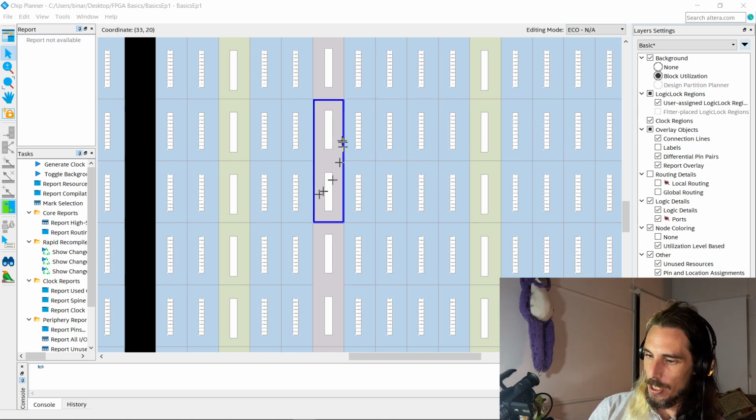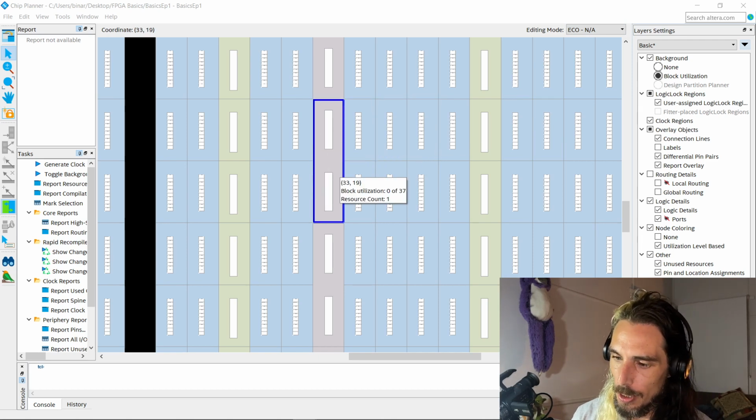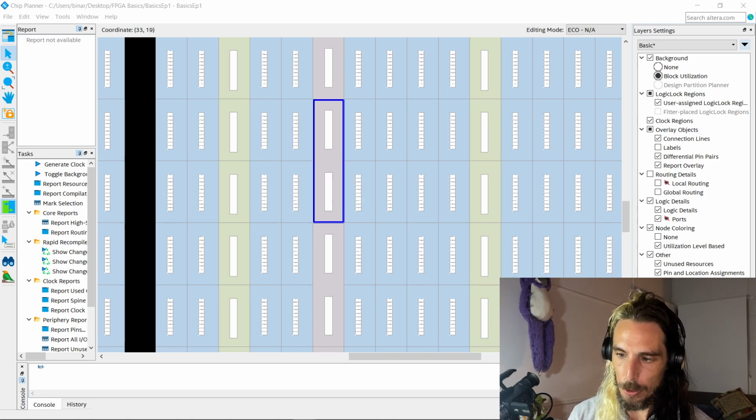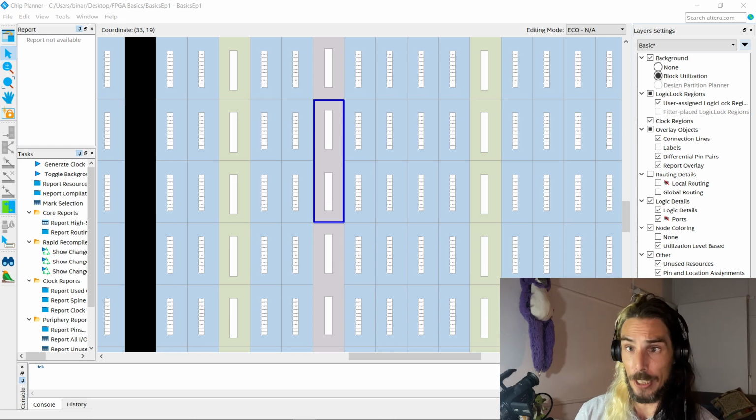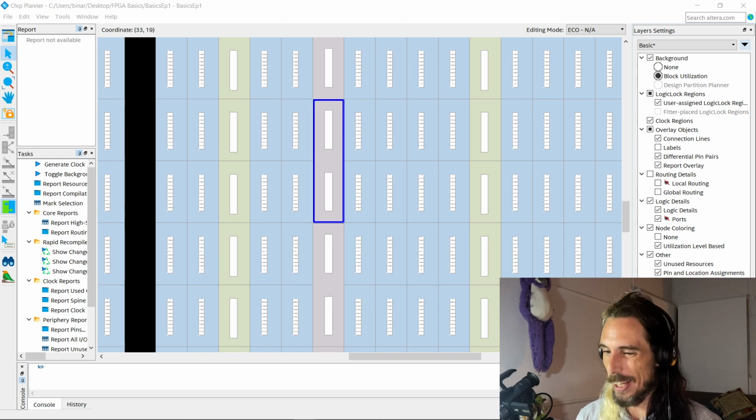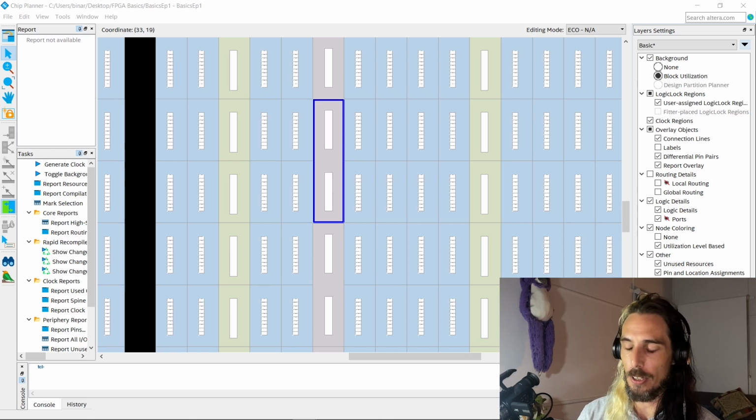Okay, so these guys here are DSP blocks, essentially. So they're designed specifically for doing maths with binary numbers. Inside each of those is some multipliers, so for multiplying binary numbers, as well as some accumulators or adders. So for doing things like FFT, so if you're doing audio signal filtering or things like that, perfect for that sort of thing.